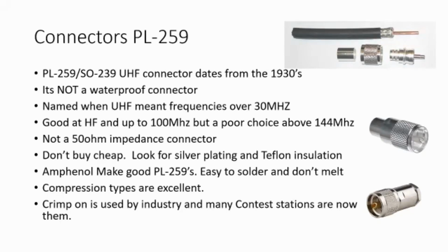It's known as a UHF connector, but it was named when UHF meant frequencies above 30 megahertz. And we now know that UHF is frequencies above about 300 megahertz. So its name does not mean you can use it at 70 cm successfully. It's a good connector at HF, and it's good up to 100 megs, but personally I would consider it a poor choice above 144 megahertz. I try not to use it above 144 megahertz.